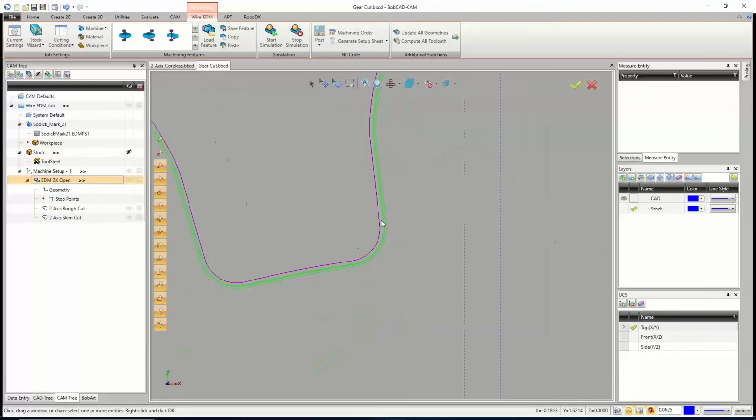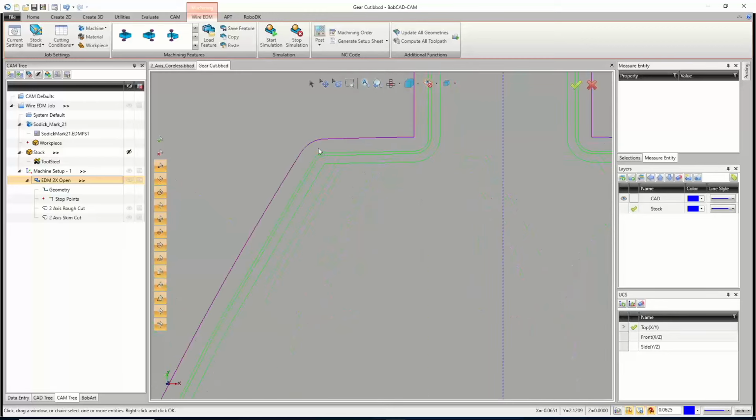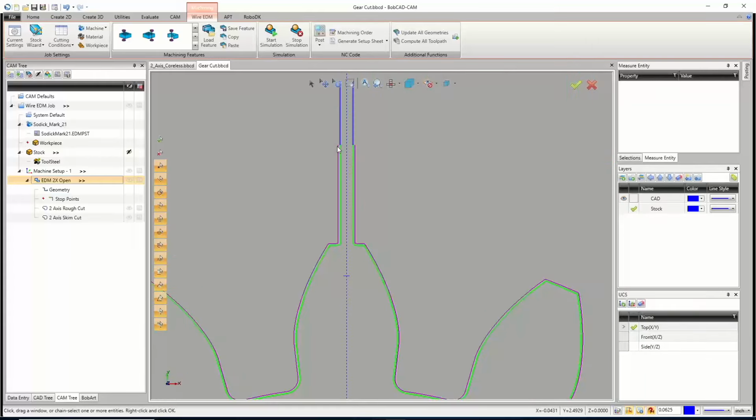And so now what you'll see is the tool path, the path itself is reversed. You can see where it's going to offset to. So if you want to make sure that you're offsetting in the right direction before you walk out to the machine, that's a good way of just visually seeing it. And what you'll see is it's all dependent on the direction of cut.